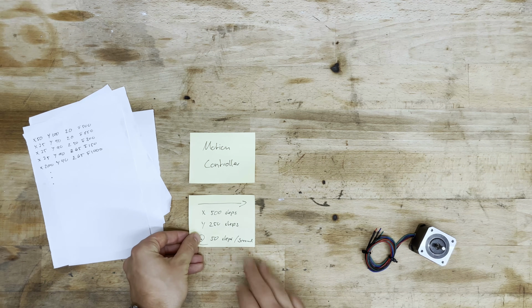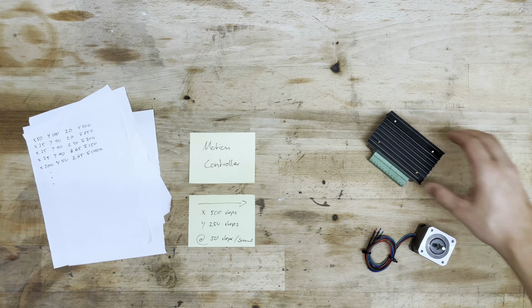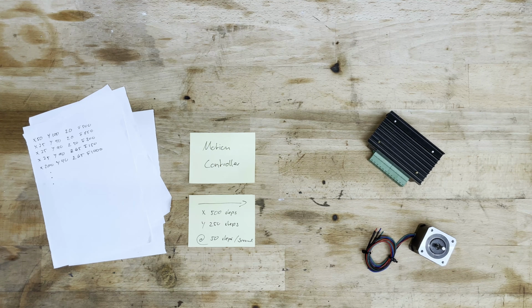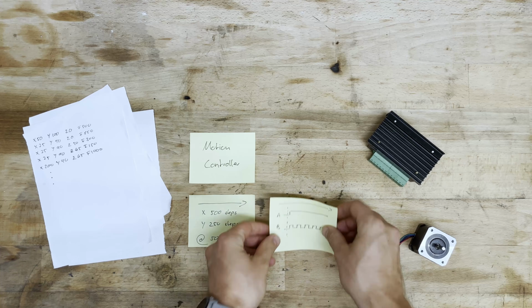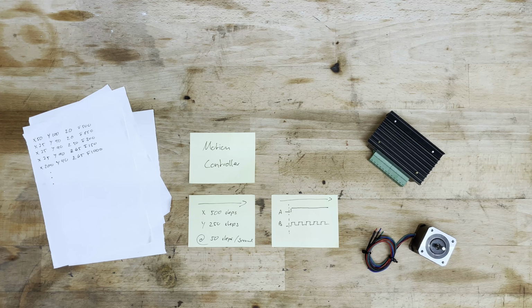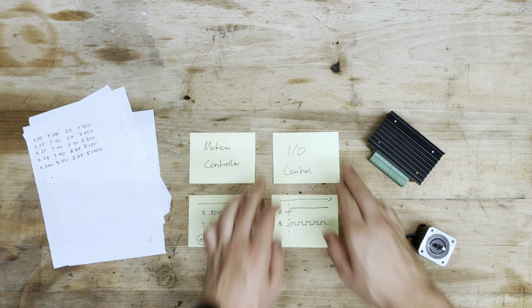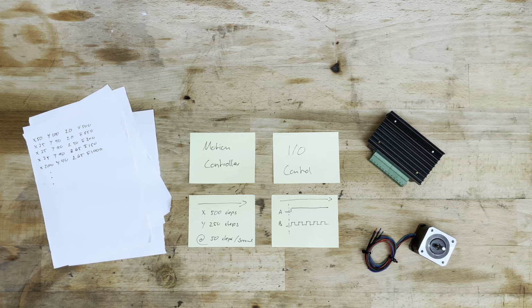This motion controller is responsible for converting G-code into motor commands and the trajectory planning. So the system will basically convert the G-code into specific instructions like X needs to move this many steps, Y that many, and it should be done at that speed. This information then needs to be sent to the motor driver, which controls the stepper by switching the polarity of the coils. In my case, the driver wants a high-low value for direction and a pulse to go a set amount. So we also need a system that then modifies the input-output pins accordingly to send this information to the motor driver. I will call this the I/O manipulation or I/O control.